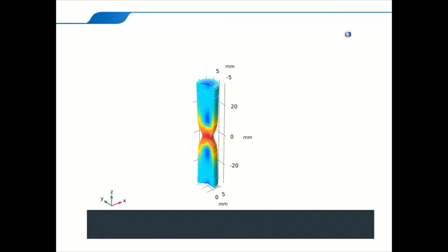You have plasticity, so you can then plot the plastic deformation and elastic and plastic deformations, stress and strain plots, whatever you would like to extract from this model. In this case, since our model is a cylinder, axisymmetric around the center axis, and since it's symmetrical up and down, like the top and bottom are symmetrical, you can just draw a rectangle which is half the length of the whole bar and then replicate it in COMSOL. You don't have to draw the whole thing and compute it all together. So we can start by going to my COMSOL Multiphysics.